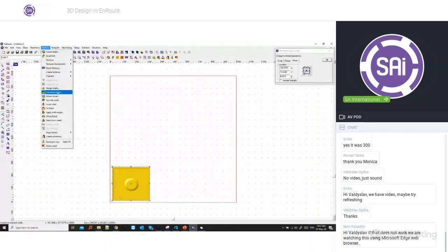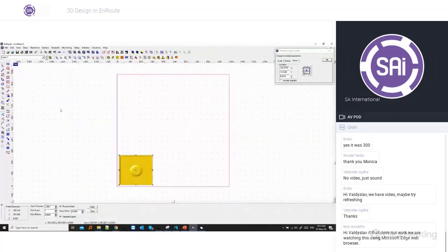Go to our surface menu, and we'll want to extract a slice from this as well. So the slice thickness, we'll choose 6.0933, and we'll choose to produce a mask and separate our slice onto a new layer.